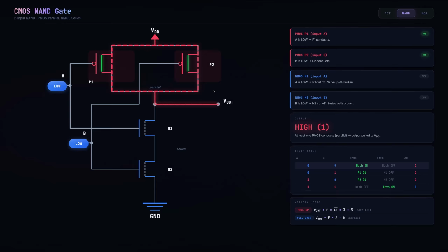All right, so notice that when you have this path from VDD to here, you can go this way or you can go this way. Because it's OR, you can go either way. So if this were cut off because this transistor is off, you still have this path. And conversely, if this one were cut off, you would still have this path. So these bubbles mean here's A, that's A bar. Here's B, that's coming up to B bar. So the pull-up side is A bar or B bar, which, like I said, is equivalent to NAND.